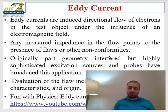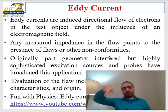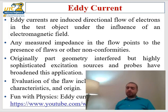The eddy currents are the same thing. Eddy currents distribute on the outer surface. That's why it's a good method to be employed to detect scratches or cracks on the outer surface of the material. Evaluation of a flaw includes flaw size, of course, orientation, characteristics, and origin. You can get a lot of information about the flaws and cracks that exist on the surfaces.